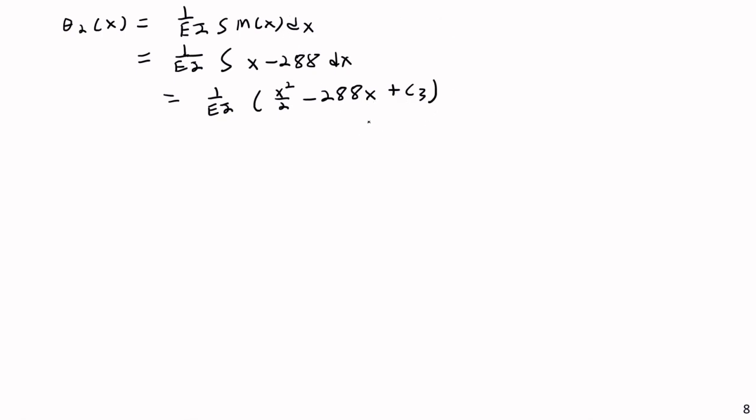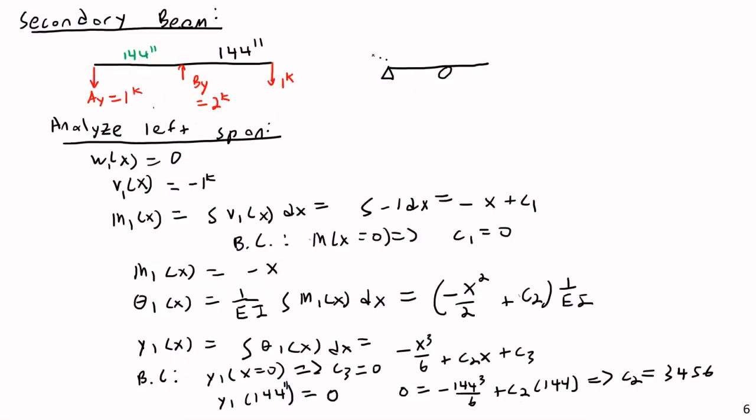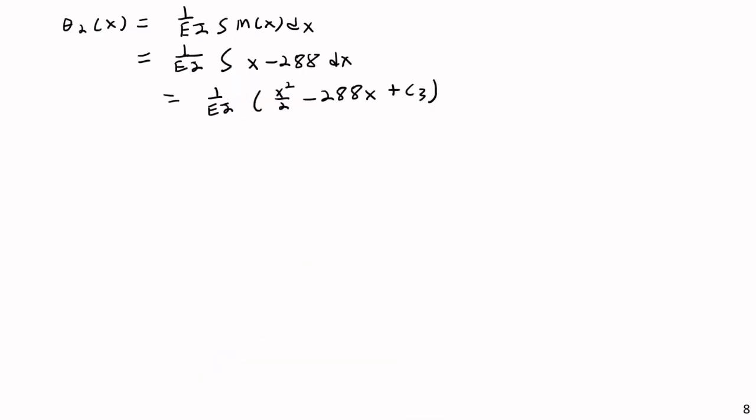Here I'm going to realize that, because this is a continuous beam, and because there are not going to be any sudden changes in geometry, the rotation at this end must equal the rotation at this end. Rotation must be a continuous function in beams. It doesn't have to be differentiable. In other words, the best way of saying it is that deflection and slope must always be smoothly changing.